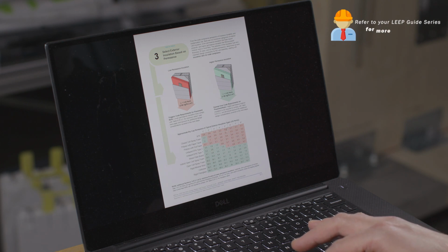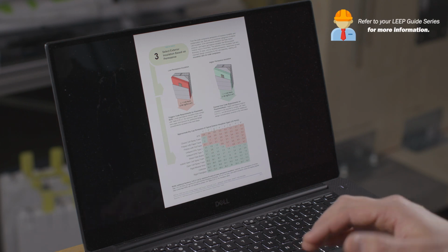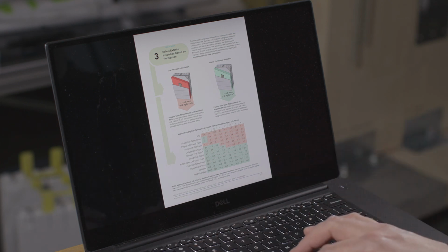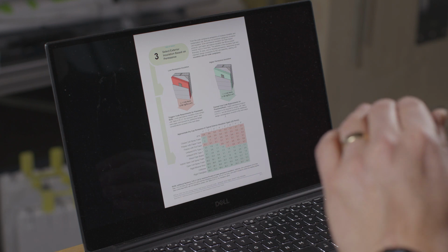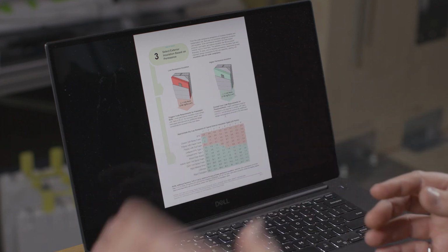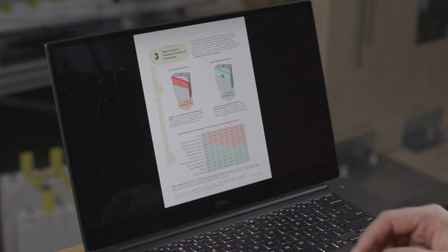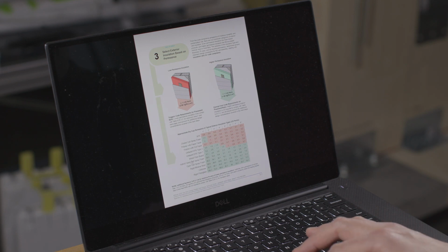The thicknesses we're usually talking about for net zero levels, in that R35 to 40 range on a 2x6 wall, that's generally impermeable. So, simplistically, foam plastic insulation can be looked at as low permeance from a simple standpoint, and things like fibrous insulation like mineral wool, wood fiber board, cellulose, rigid fiberglass, those tend to be vapor permeable.